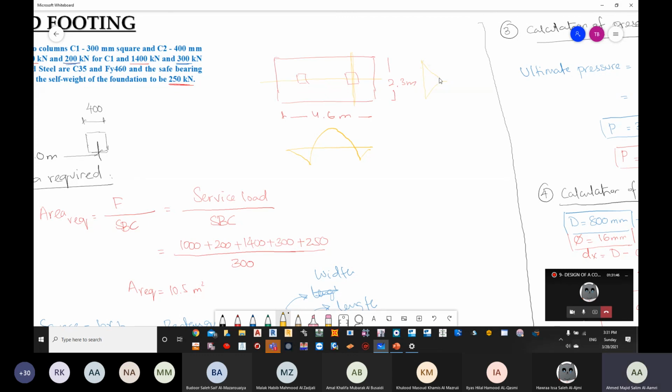If you see, you will see one column. You will have one distance here, and you will have one distance here, L1 and L2. You will be taking the higher of the two to calculate the moment on the other side. We have top reinforcement here. This column side is representing your top reinforcement. This span moment is going to be representing your bottom reinforcement.